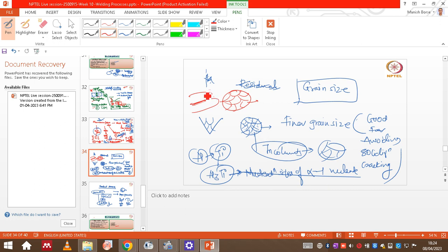In that particular volume, obviously the solid fraction is the same. So in that solid fraction, if multiple grains and grain boundary areas are there, obviously the solid will be distributed at certain grain boundary areas, right? That means it will prevent the continuous liquid film formation.